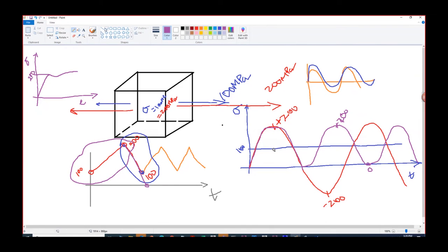But what happened is that since we have done only the linear analysis without considering any plasticity model, the stress has gone up to 300 here. This is not really the correct stress. So that's where the plasticity correction comes into the picture. When we do a plasticity correction, this stress value will come down.